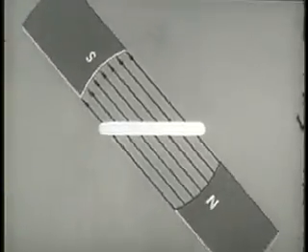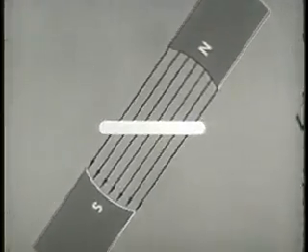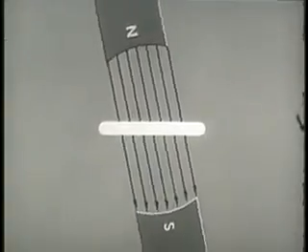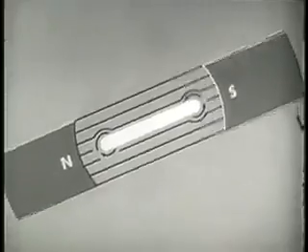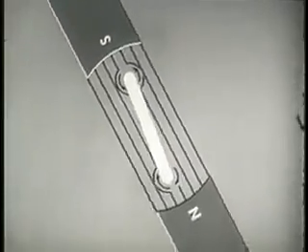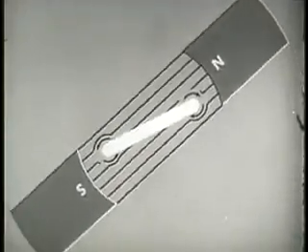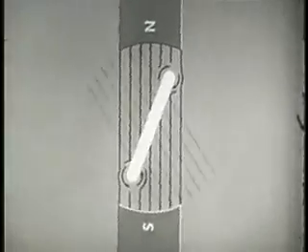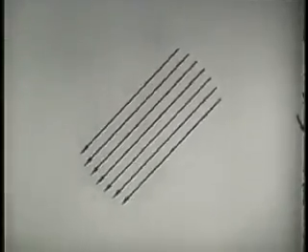For if the rotor stops while the field continues to turn, relative motion will have been re-established. Lines of force are being cut once more. An EMF is generated and the resultant magnetic field will cause the rotor to move again. So far, we have rotated the field by physical means, which is impractical. It is necessary to find a way to rotate the field electrically.